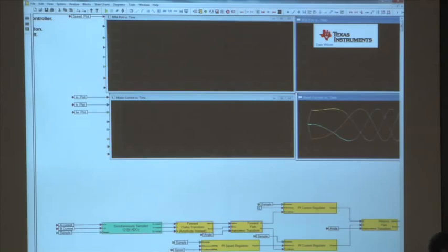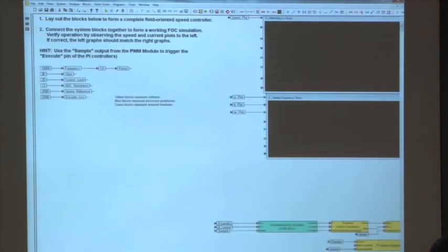Now, the only thing that we don't have yet is the reference speed that we want it to go to. If you look up at the top, I have a bunch of global variables defined up in the top left-hand corner of the simulation page. You can see where I've already defined the PWM frequency, PWM period, the bus voltage, my current limit I've set to 20 amps, A to D resolution. There's also something there called speed reference, which you can see I'm setting to 2,000 RPM.